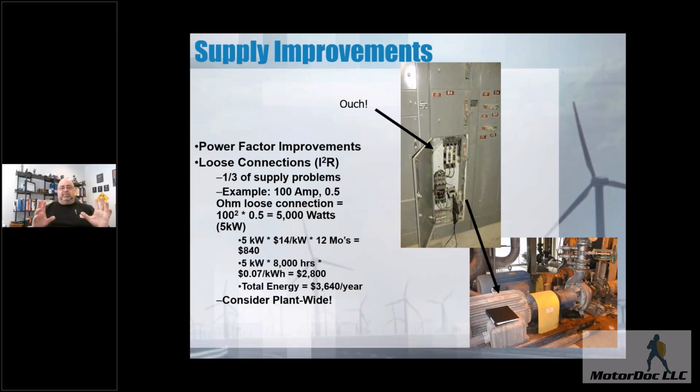People forget, everybody keeps talking about voltage and stuff like that, but even in IEEE 519, which is a harmonics thing, and I'm not going to touch too much on harmonics unless I have some time at the end. Harmonics have an opportunity that is tremendous now because of all the electronics we put in place. In 1995 or 1997, it was determined to be 2%. And that is before all of the electronics we put in place. Now everything is electronic. So we're seeing improvements exceeding 10% in most facilities just by cleaning up grounds and neutrals.